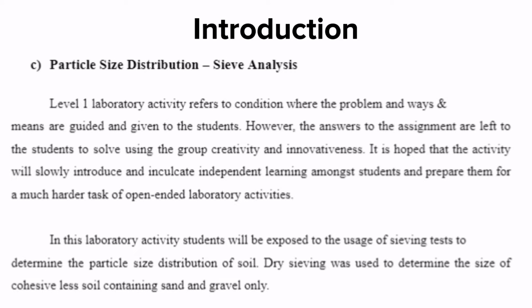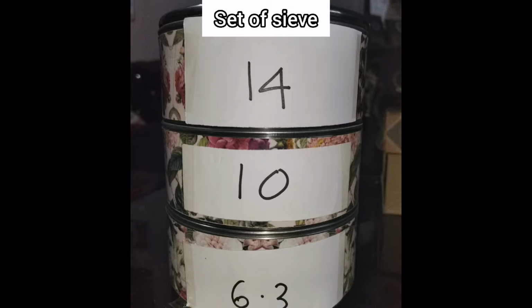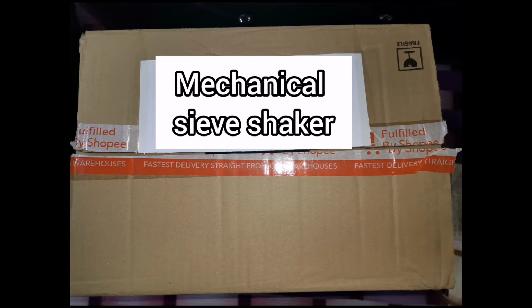The third test is particle size distribution, sieve analysis. The objective of this test is to determine the percentage of different grain sizes contained within a soil. The apparatus needed for this test is lid, soil sample, cleaning brush, scale as balance, bowl as pan, tiffin carrier as set of sieve, and a box as mechanical sieve shaker.